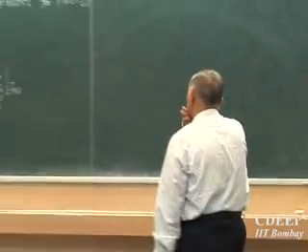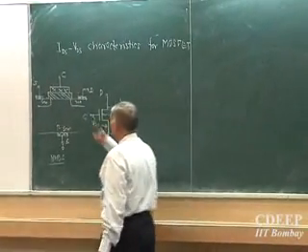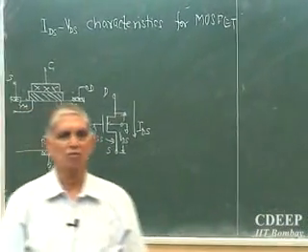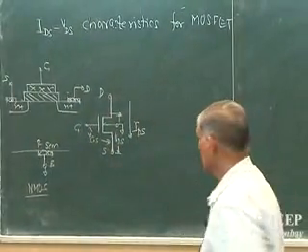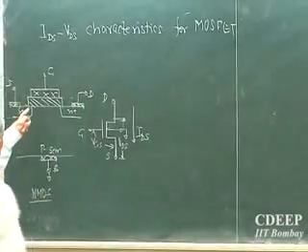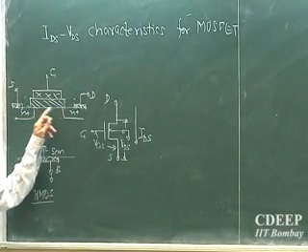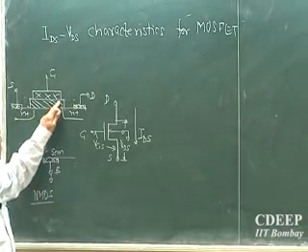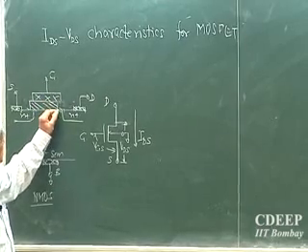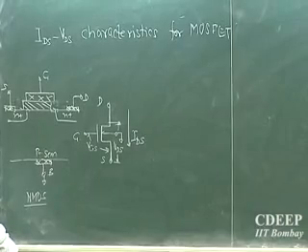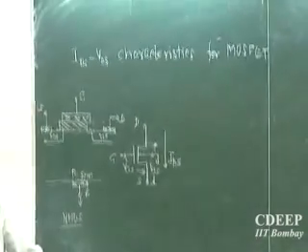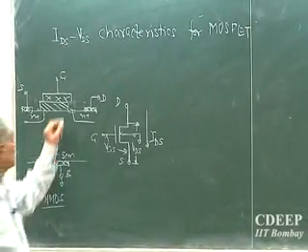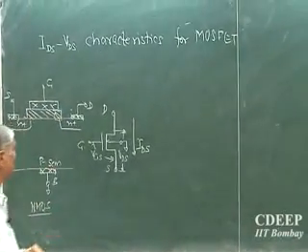If I had to do this, yesterday we already said that if I put a VGS higher than the threshold voltage, then I will see an inversion layer of electrons between source and drain. One guaranteed I did that: this oxide was covering part of the source and drain, so that the inversion will occur throughout the source and drain region. Let us say if this would have been here, this region probably would not have got inversion because there is no gate oxide there. So the mask requirement, just for that I said, I must cover source and drain areas partly. So this is something which is mask related, but just to give an idea why covering.